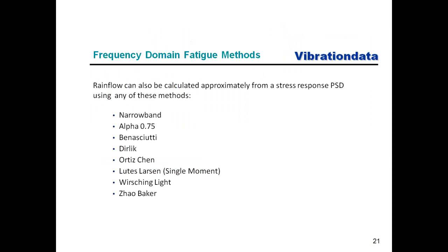We're going to switch gears a little bit. We're going to stick with that same beam example, only now we've got something new for today. We're going to do rainflow counting, and we're going to do it in the frequency domain. So rainflow counting can also be approximated via a direct calculation from a stress response PSD.